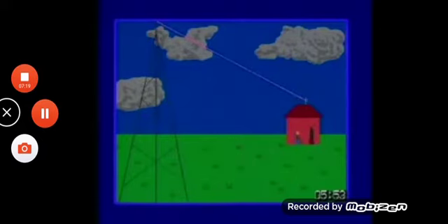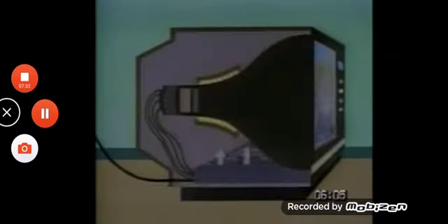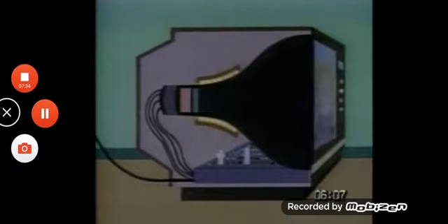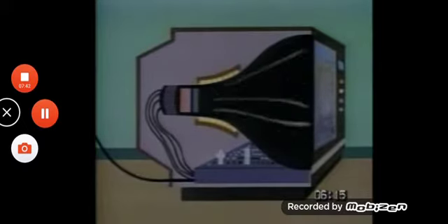At the receiving end, these impulses are picked up by your antenna, and they go into an amplifier in your set, and are sent to an electron gun which is in your TV picture tube. This gun sends out a beam which goes back and forth across your screen. This is what happens at the receiving side. Your screen also has lines, and the beam scans every other line 30 times in a second.